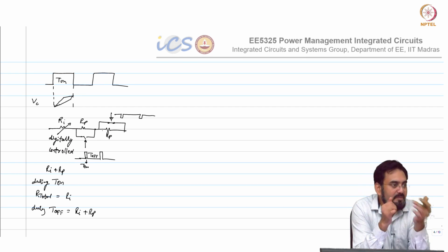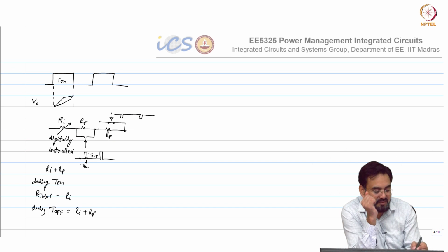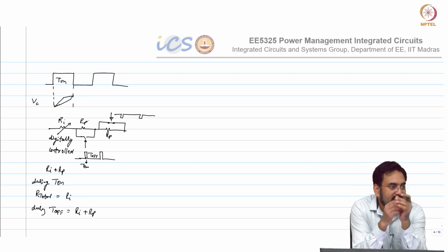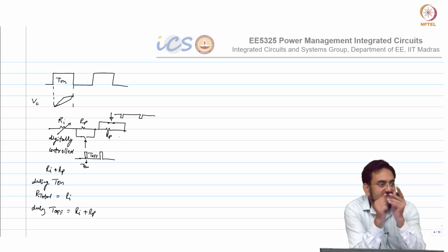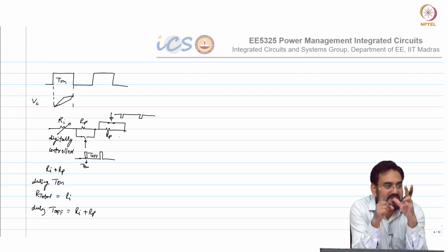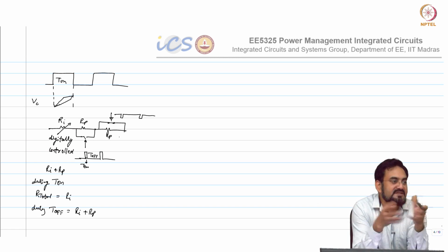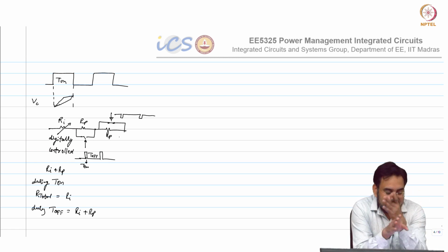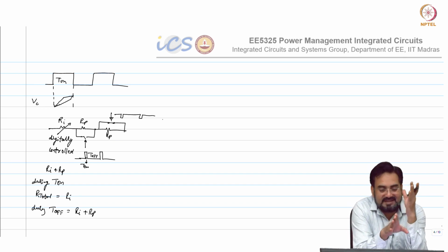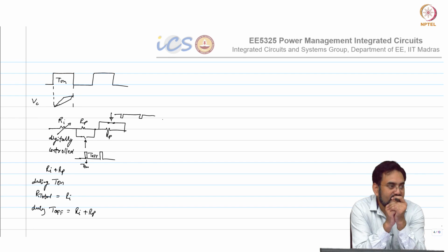So depending upon up or down coming, you have to control one of these two resistors, and it will change the resistor value, or you can say it will lock with the pulse width for which the two frequencies are the same, and since this time is constant for this PWM, they will exactly lock at the same frequency.